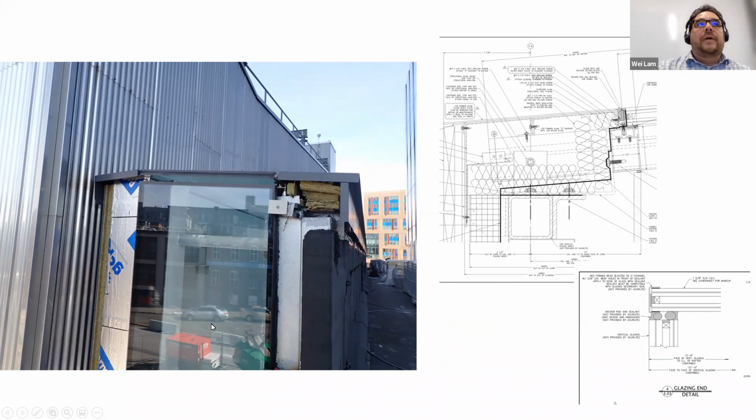I don't know if you caught the fact that the ends of this are glazed, right? So there's some glass here supported below that comes up and meets that. But if you can see it here, there's a fairly large joint between the glass, and that was anticipated to look maybe plus or minus 3/4 inch. So geometrically, this is a pretty complex assembly.